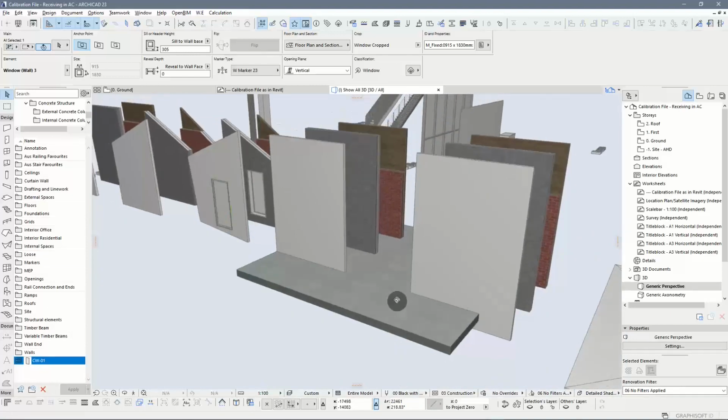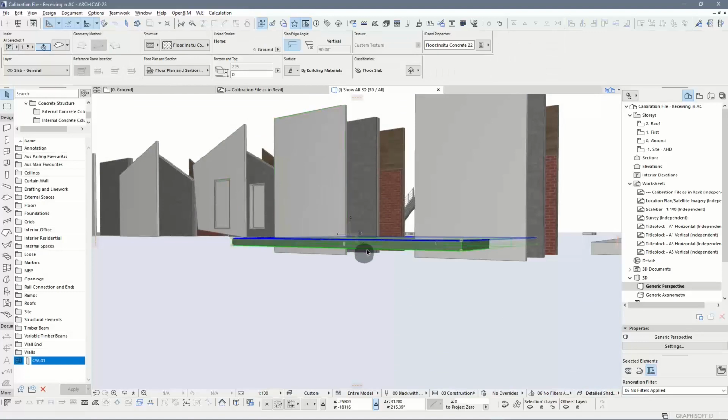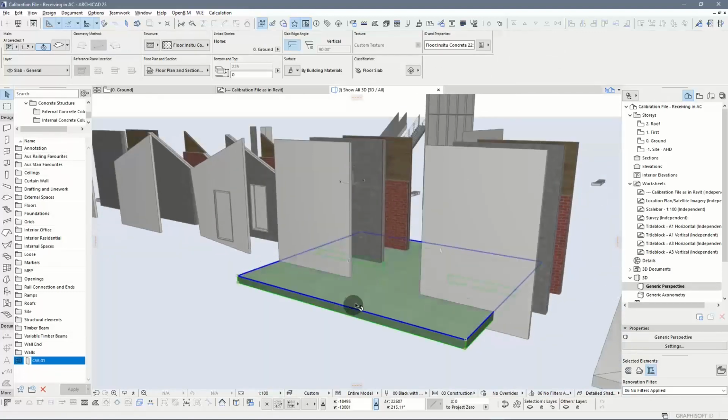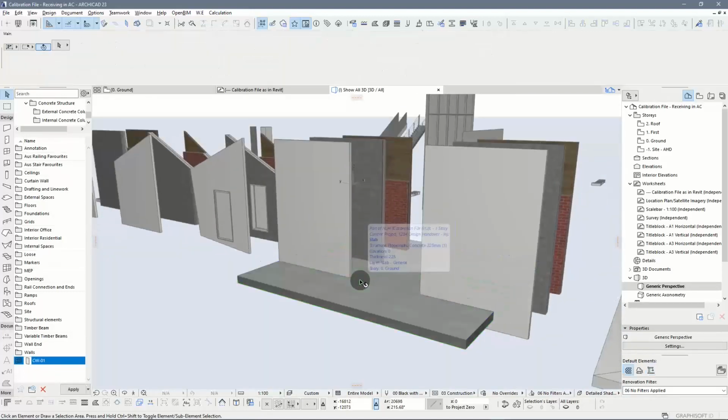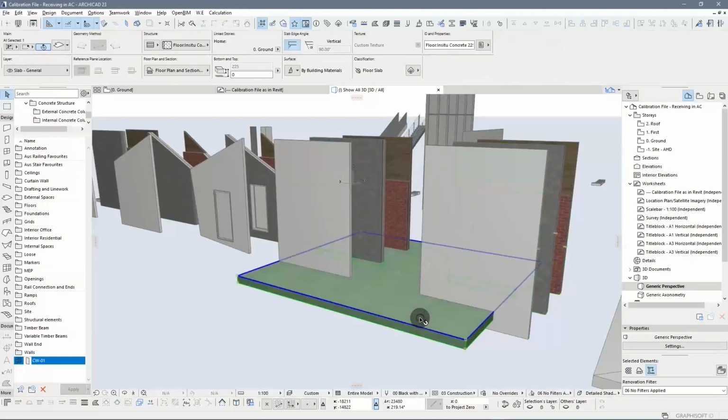Let's take a look at this, where now we have an interface between those elements and these elements. Note the following: because we have created a match in the building materials, now Archicad's priority connections between building materials will take precedence. So these are still going to be walls, not B-reps.